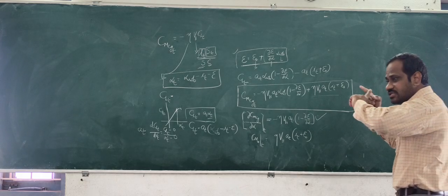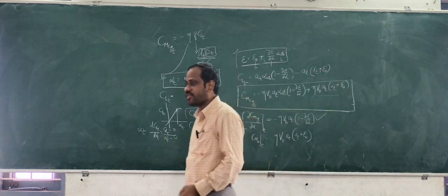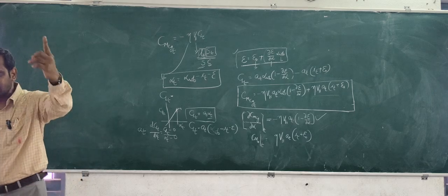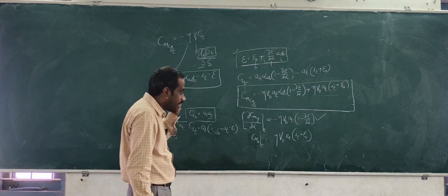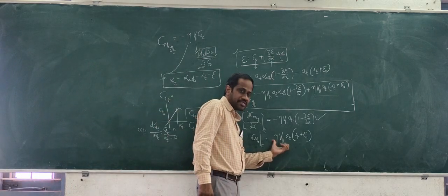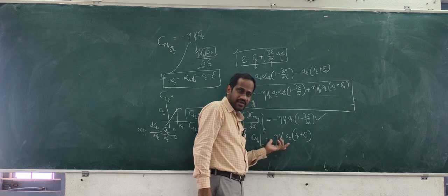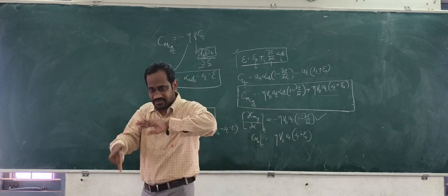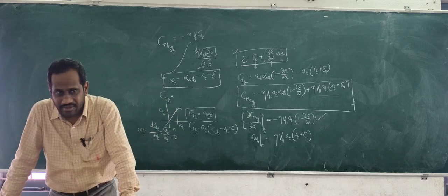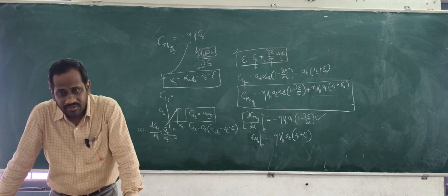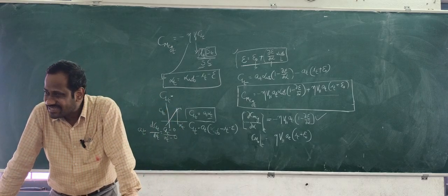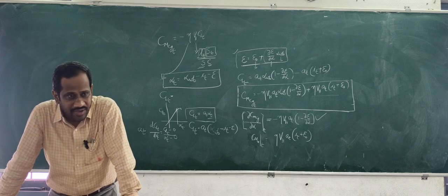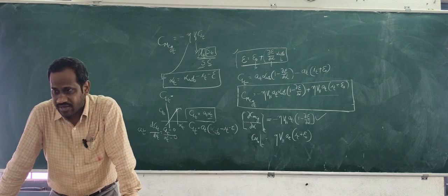Then only the negative value contributed by the wing and positive value, how much amount of positive value you need, all of the parameters will dictate. If there is a trimming required or adjustment required in the design itself, tail setting angle, if you just take a suitable or convenient value, then you can achieve the balancing of equilibrium angle of attack of aircraft as the positive angle of attack.